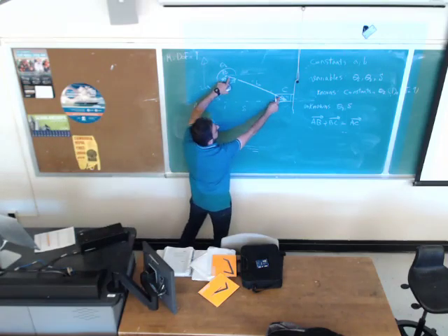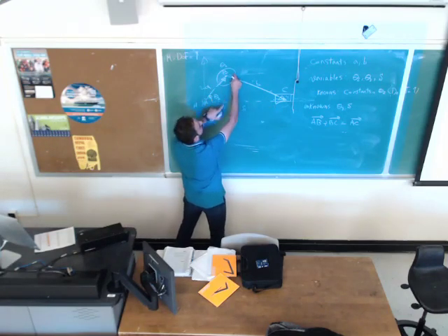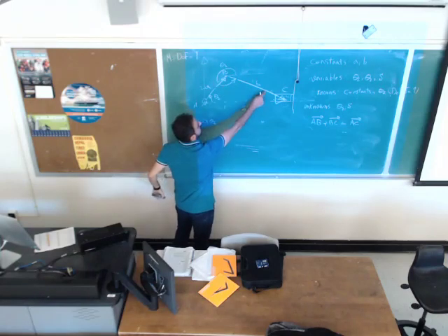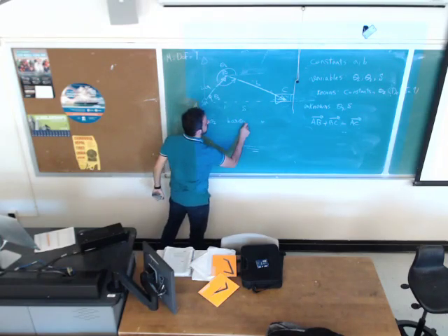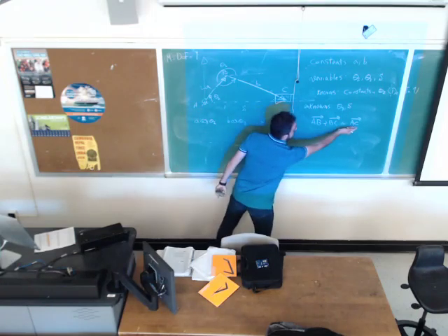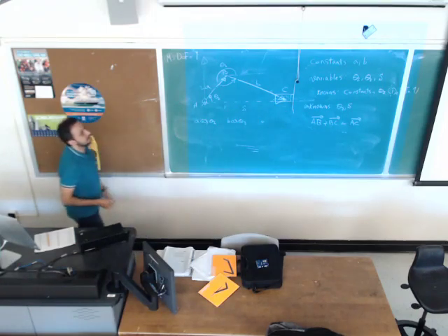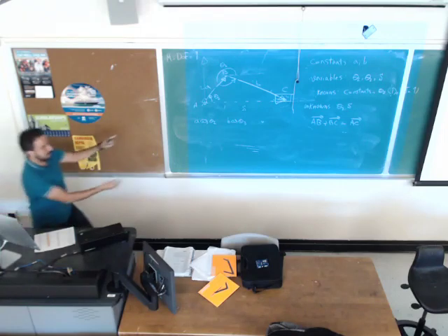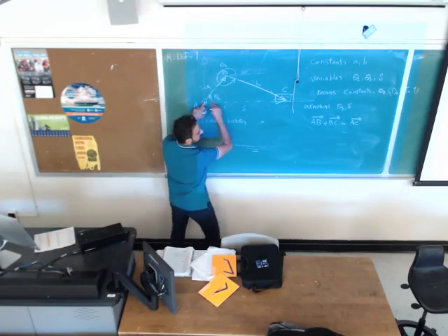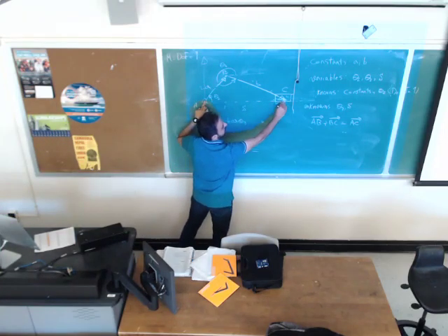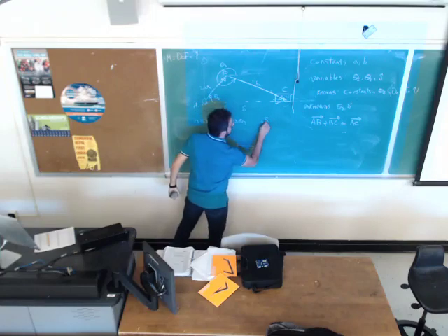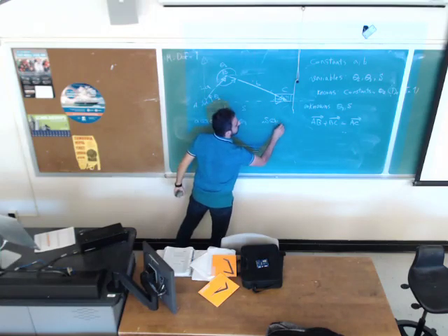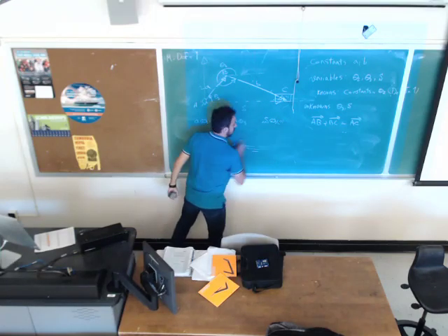Whatever is the length of the link, whatever is the angle of this link with the ground, which is theta 3: B cosine of theta 3. Whatever is the x component of AC. AC is parallel to the ground. The entire of this vector is going to be the x component of that. It's going to be S, or you can say S cosine of 0.